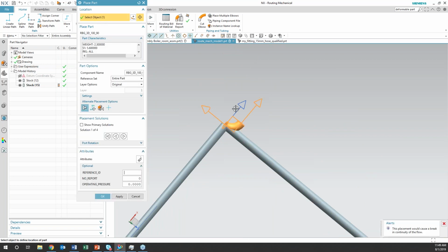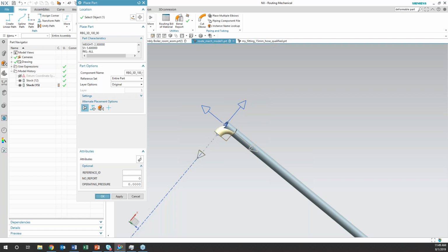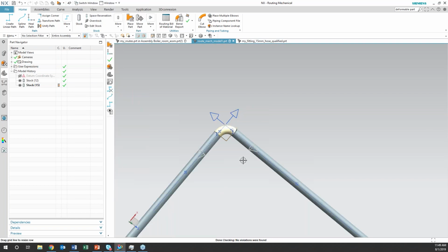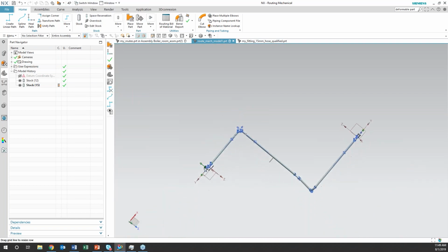Okay, let's reselect that to make sure to really get that routing control point. If you don't get that routing control point, it throws that corner off into space. So you need to have it there to replace your routing.